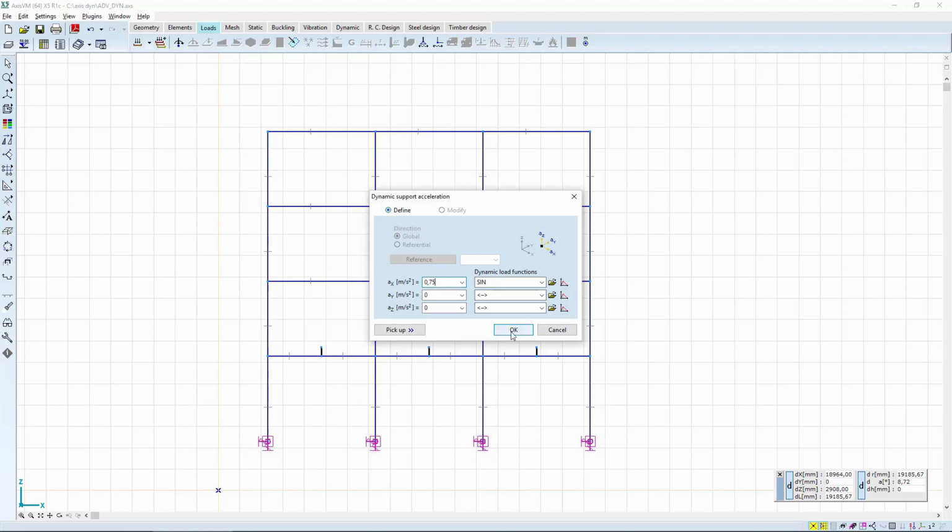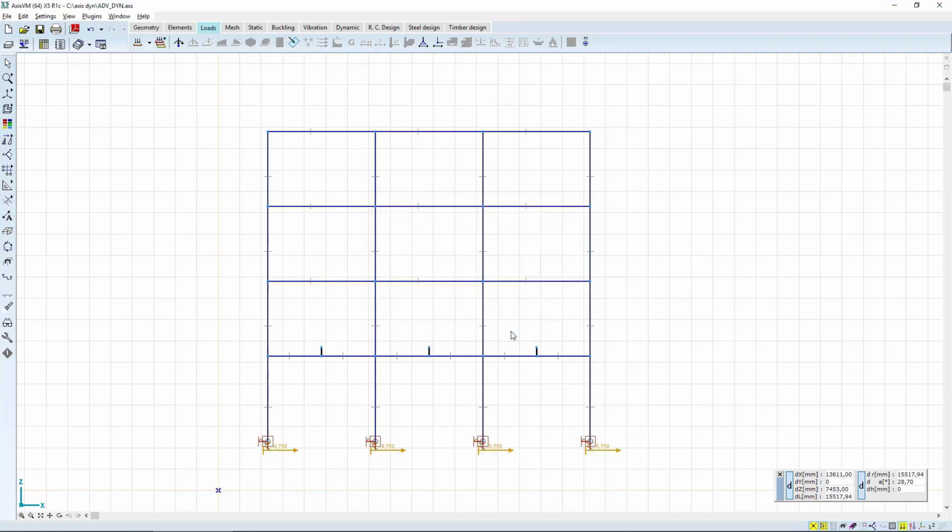The applied dynamic loads are indicated by the arrows under the supports, and the values above them are the set constant acceleration values. Change to the machine load case to model the dynamic effects of rotating industrial machines. We will use a time-varying concentrated load to simulate the effect of rotating machines with simultaneous phase motion.